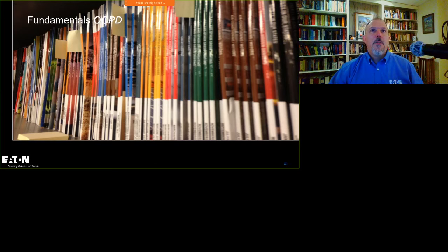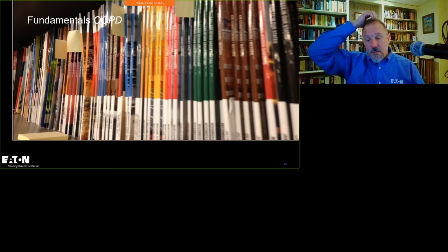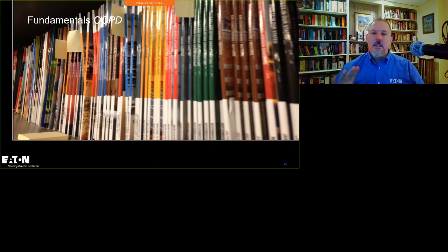What are the safety precautions in circuit breakers? We're going to talk a little bit about that. Settings, changing settings and whatnot. A lot of that's done, hopefully, without it being energized. What could happen if you change some of those settings is you could cause a trip, and that might be ungood depending upon what's going on. And not just because of the breakers, because of whatever you're serving. There are a lot of reasons why you should probably plan.